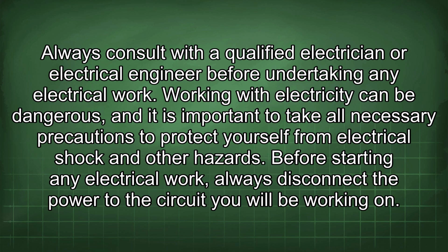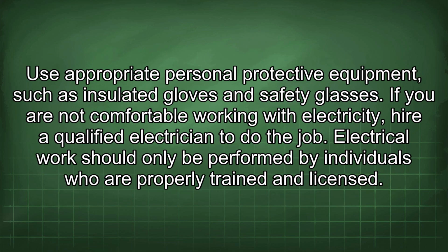Working with electricity can be dangerous, and it is important to take all necessary precautions to protect yourself from electrical shock and other hazards. Before starting any electrical work, always disconnect the power to the circuit you will be working on. Use appropriate personal protective equipment, such as insulated gloves and safety glasses.